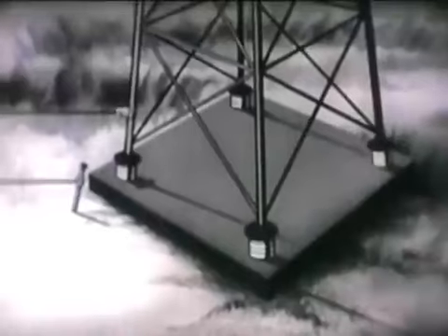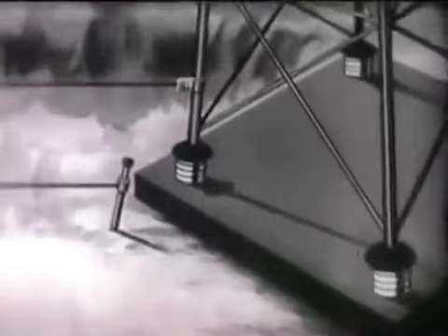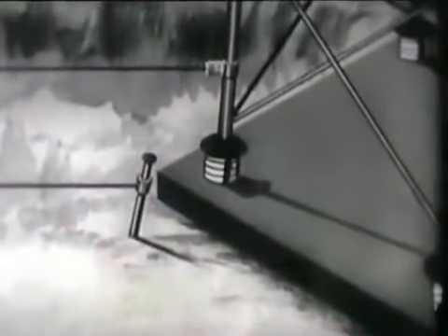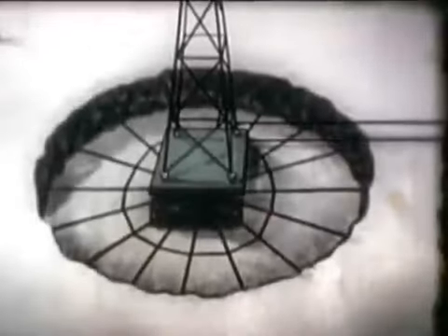The efficiency of a quarter wave antenna depends largely on the nature of the ground. At installations near the sea or in salt marshland, the Earth's conductivity is excellent, and a simple metal stake provides proper ground. In drier regions, a system of conductors installed at the base of the tower may be required.